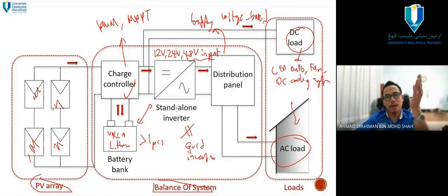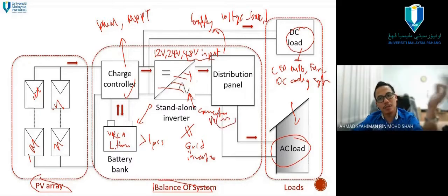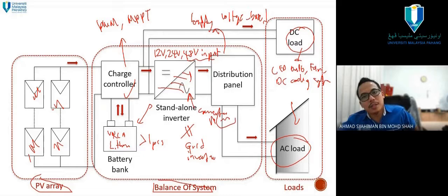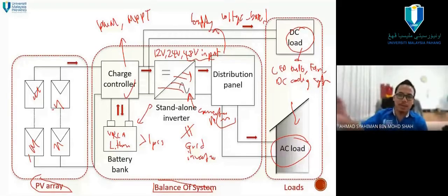So kita boleh avoid because when the energy goes through the inverter, of course they have the converter, they have maybe capacitor, resistor and so on. So that one will contribute to the loss, it will be dissipated as the dissipated power kan, as a loss. That's why if we can use directly with the DC load, then we can avoid the inverter. We're not paying with the inverter efficiency because we directly use the load. So dia tak ada issue loss lagi kat situ lah.